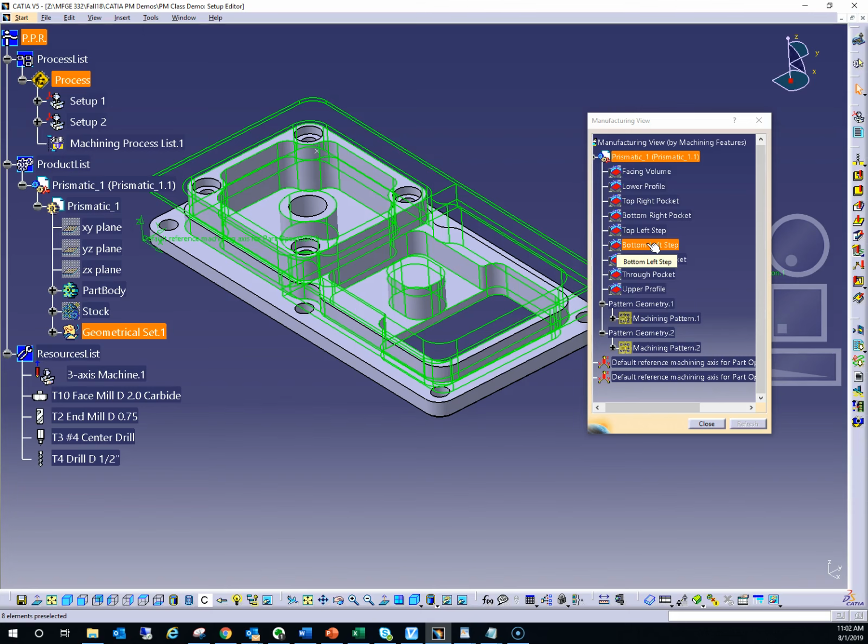And again, this is one of the first steps one needs to go through. There are obviously choices here. One of the choices we made was to machine this pocket before this region over here. We could reverse that order, certainly. So there are choices that need to be made, and sometimes you have to go back and redo things because it might be more efficient once you've completed.